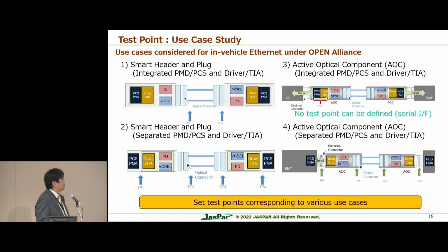But with fiber optic technology, we need an electrical-optical converter in order to change the electrical signal to an optical signal by using a driver, and the opposite side is a TIA with the photodiode. So in that case, this one is a separate component. Then we need to have some test points between the PCS, PMA, and the drivers.